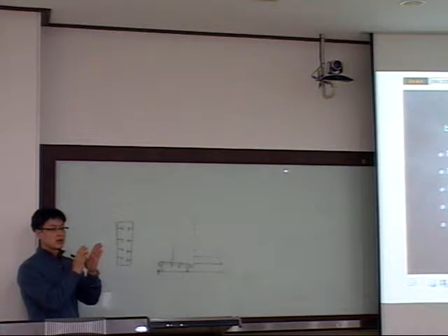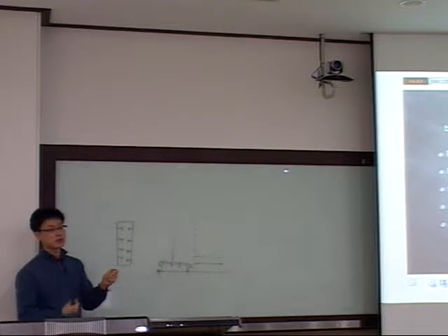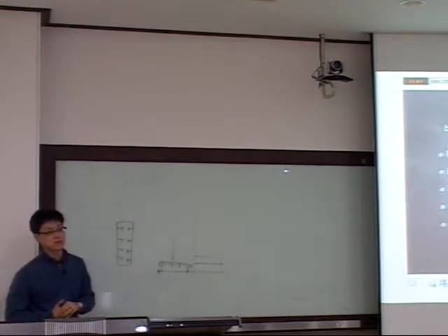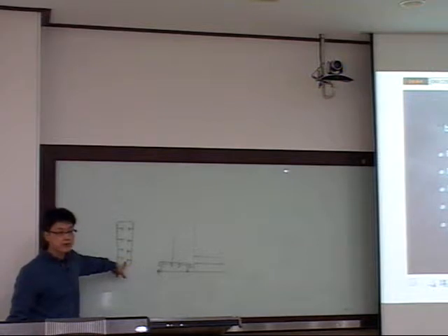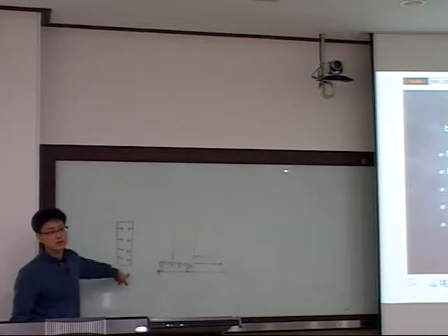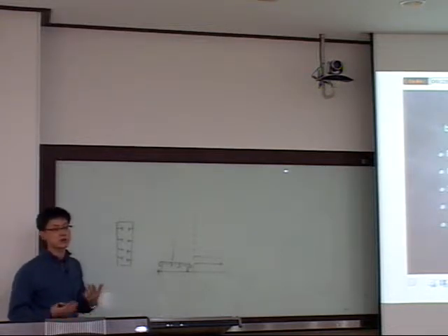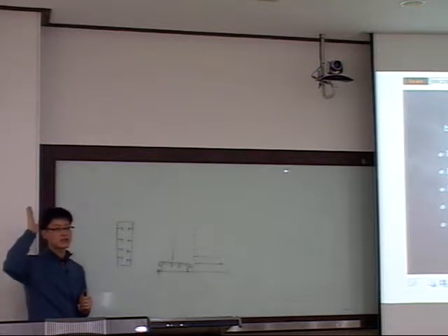For example, we are utilizing steel plate, but it's not that stiff. In order to increase the stiffness, we have to put in stiffeners. Because of that, the ship structure is very complex. But if you use this kind of prefabricated plate, it is just stiff enough, so you don't need any webs or stiffeners at all, which can greatly reduce the work required for stiffeners, webs, welding and other things. That was his idea in his seminar, so I raised a hand.